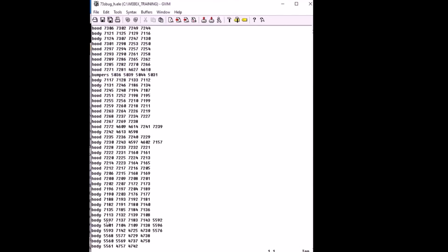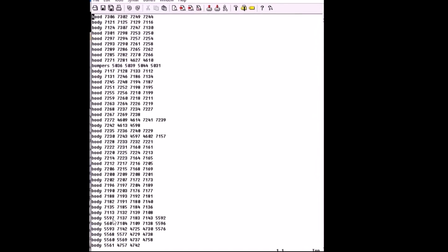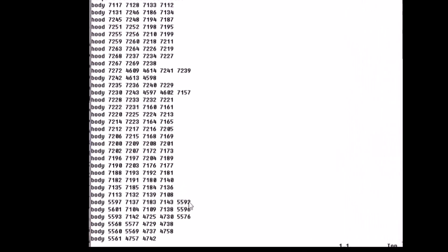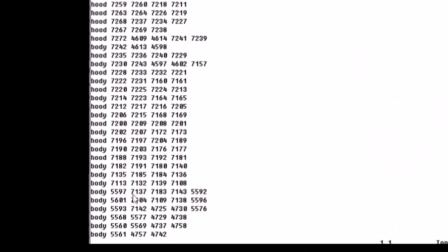And when you see an example of a polygon that has more than 4 nodes, what TrueGrid does is breaks that up into 2 polygons. The assumption is that when there's more than 4 nodes, it's planar. So there's no ambiguity as to how to break that up into smaller polygons.